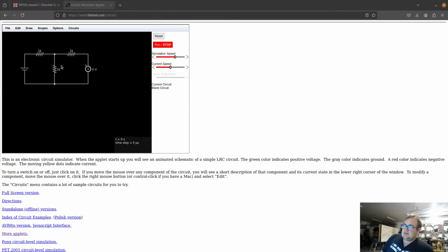Since these two are in parallel, they're going to show about 500 ohms in total. So that 2/3 of the voltage will get burnt across here. Since we're dealing with a 12 volt one, that would be 8 volts. So I would expect 4 volts to be across here and here.